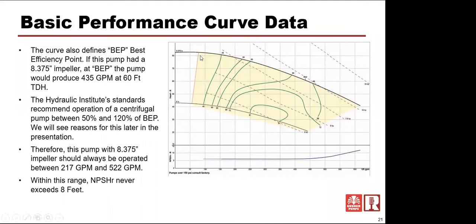But you never want to operate your pump on any kind of regular basis below about 50% of flow, which is 50% of BEP, or best efficiency point, which is 217 gallons. So it's somewhere in this ballpark right here. You never really want to be operating back here. And again, it's all resistance in this system that determines where you're going to operate on this curve.